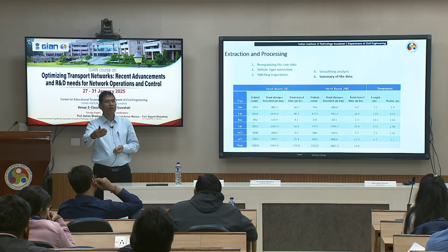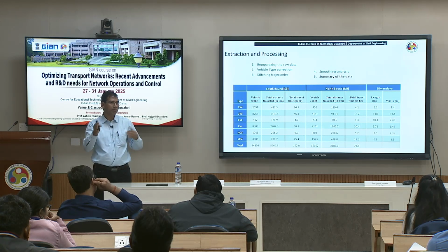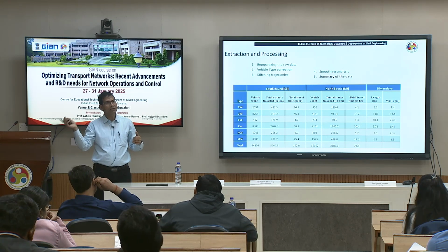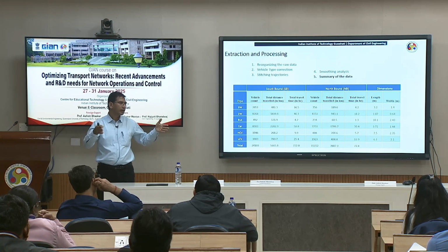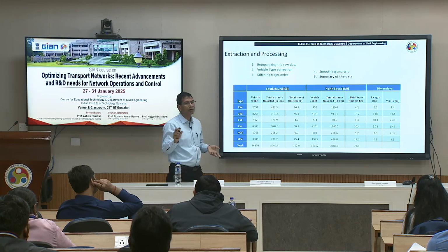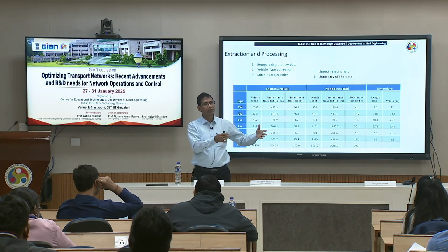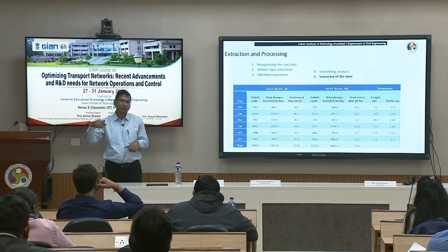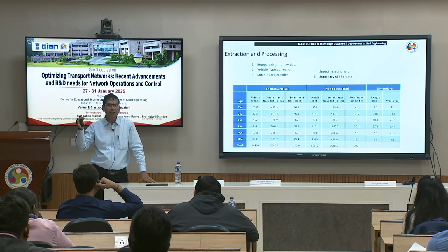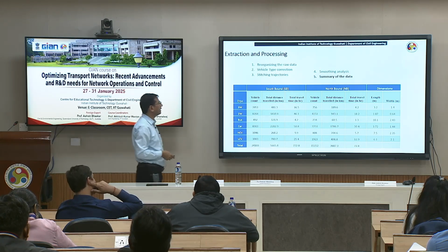Not only developing the model, once you develop the model, you need to calibrate it. In order to check what lateral acceleration values are available in the field, you need to match with your simulated trajectories. Out of maybe a 1 hour or 1.5 hour video, you keep maybe half an hour only for validation. That will not be part of the simulation development. Once your simulation model is developed, the remaining part you use for validation, so you can see whether your simulated trajectory is matching with the observed trajectory or not.